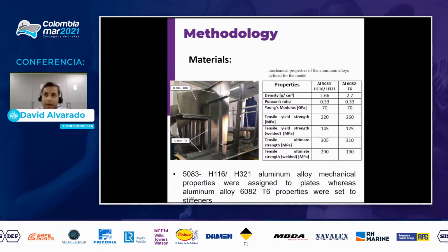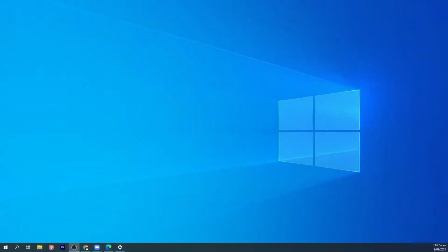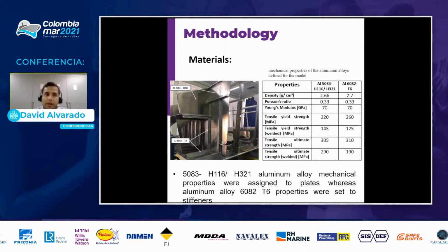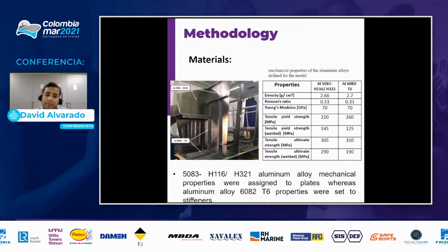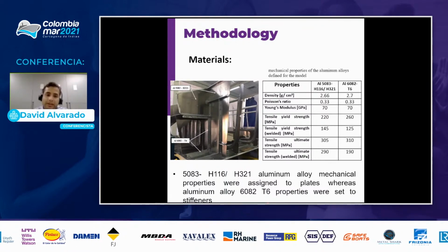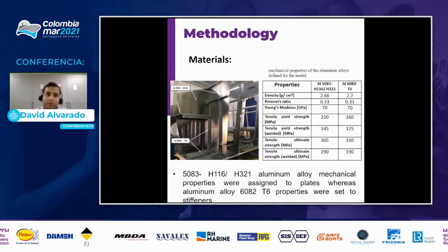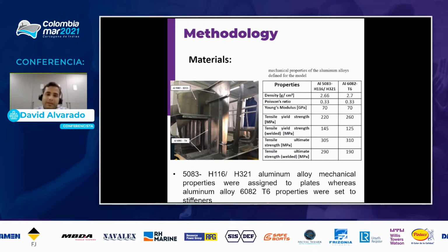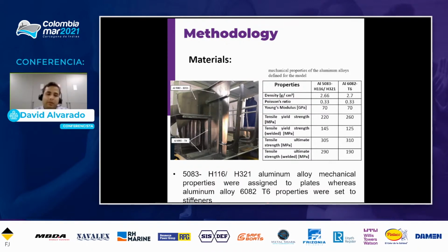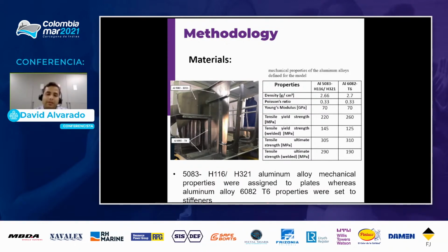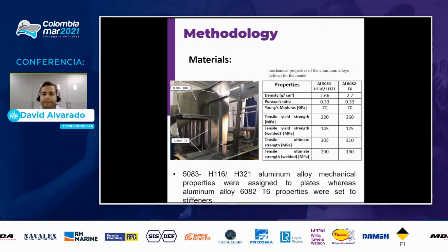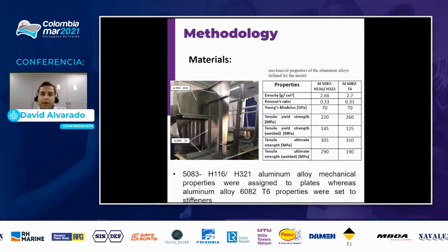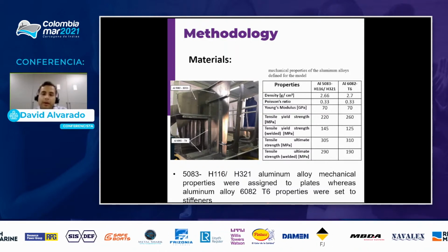According to the research, the effect of temperature is a local effect very close to the welding regions, and the 5083 aluminum has a limited effect. It doesn't go lower than 50% of the mechanical properties, which is different to what happens with profile aluminum, which is very sensitive to temperature. The 6000 series is actually better because it can be bent and used as profiles because they are extruded.